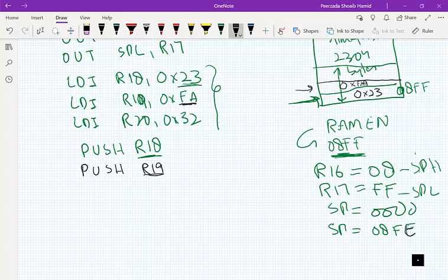And now the question is, how will pop, that's retrieving data from the stack, work? One thing you should remember, that we can't retrieve any data from the stack. We can only retrieve what is at the top of the stack. So if I write pop, because in pop I am not giving any address of the stack, I am just writing pop and giving the general purpose register where the contents that have been popped will be stored.